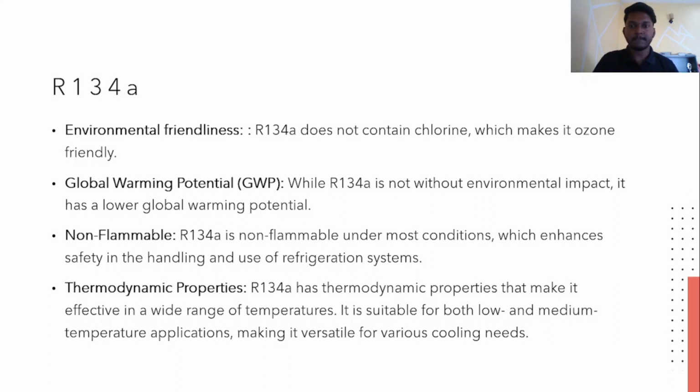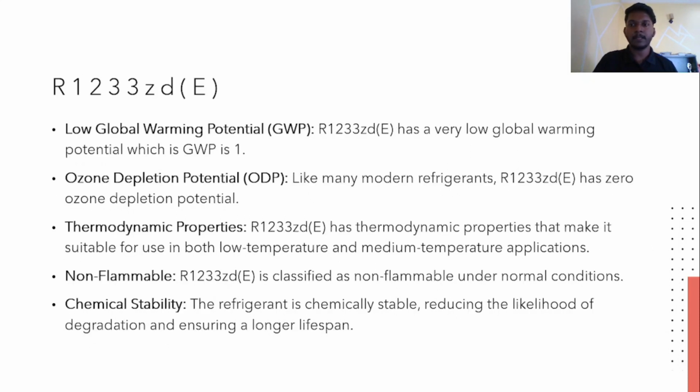Thermodynamic properties. It has thermodynamic properties that make it effective in a wide range of temperatures. It is suitable for both low and medium temperature applications, making it versatile for various cooling needs. Next is our refrigerant R1233ZDE, low global warming potential. It has a very low global warming potential, where GWP is 1. Ozone depletion, like many modern refrigerants, this refrigerant has zero ozone depletion potential.